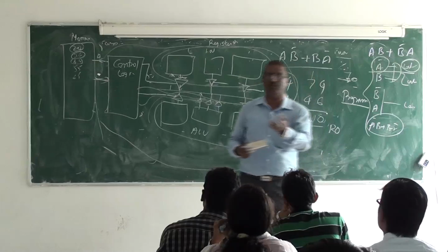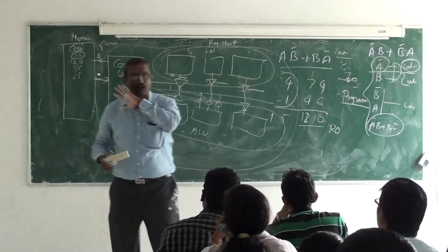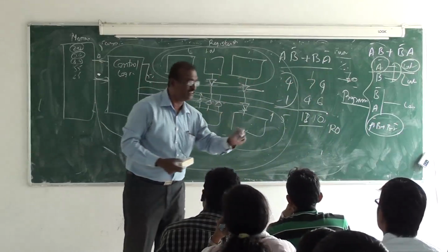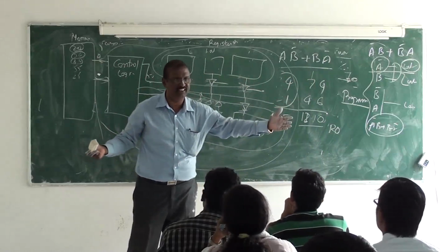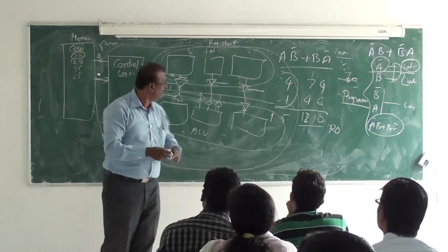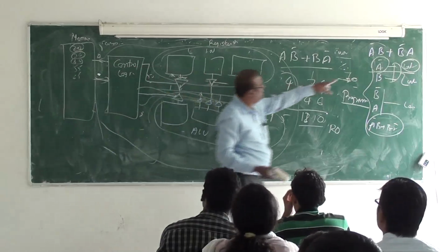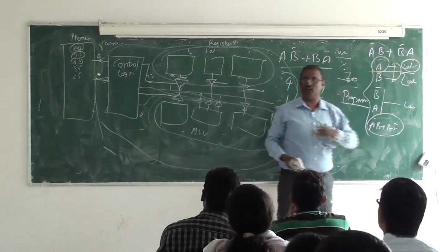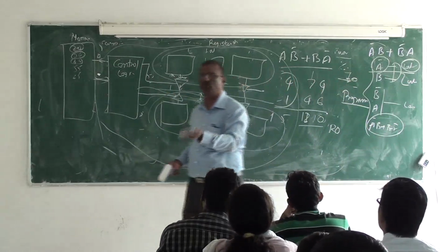In the PLD, the drawback is you have to make the entire circuit at once. Before I start using it, I have to configure the entire circuit. But the advantage is it is fast; things will go in parallel. The problem with the microprocessor is you do one by one, so the drawback is it is slow.